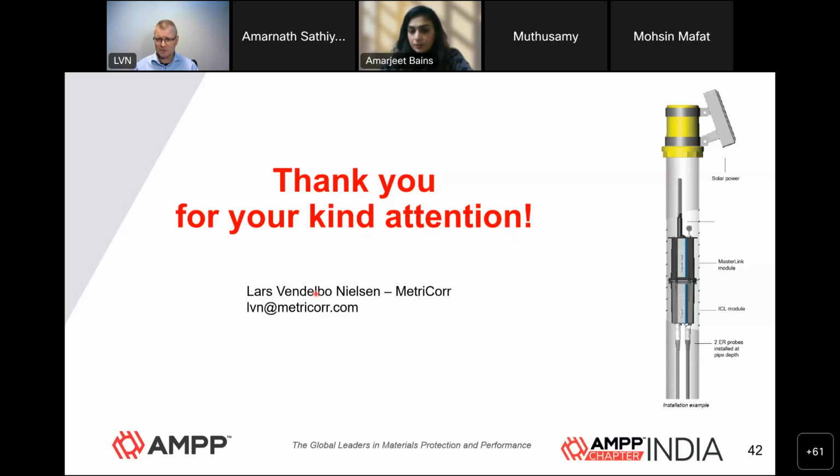There are some guidelines on how to design coupons and how to apply and use them in connection with cathodic protection measurements. And furthermore, we are currently within AMPP developing a standard called field techniques for evaluation of AC, and that one gives you more elaborate guidance on how to design, apply, install and interpret results from probes in relation to pipelines as such.